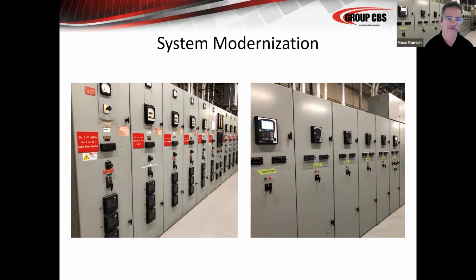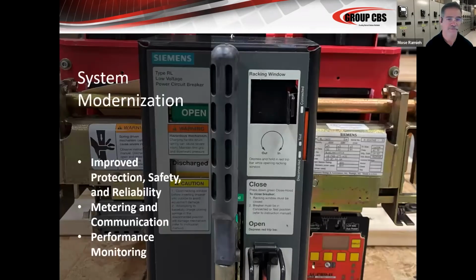Yeah, it is always there. There are always customers and situations and systems where, yes, it is a challenge to take an outage on a particular device. And in some cases, I like to use the phrase that any activity is better than inactivity. So, just using the breaker picture, if you say, hey, Mose, I can't shut this circuit down for you to do a complete test on this breaker, okay, well, can I just simulate a fault to the trip unit, trip it, and then close the breaker back? Yeah, I can take a 5-minute outage.